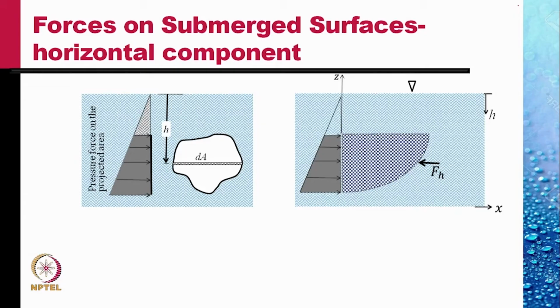At depth h, let us consider an area dA. The pressure on this area dA is rho g h, and the force is rho g h times dA.